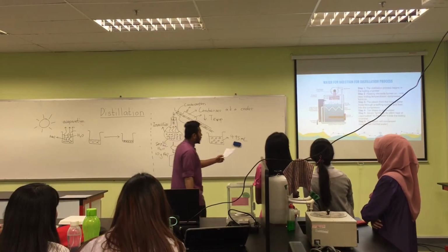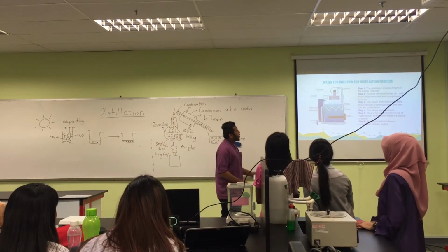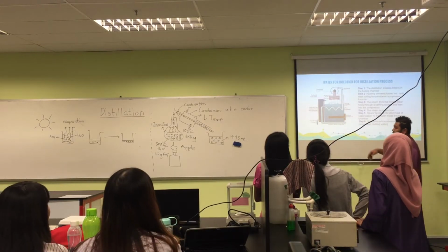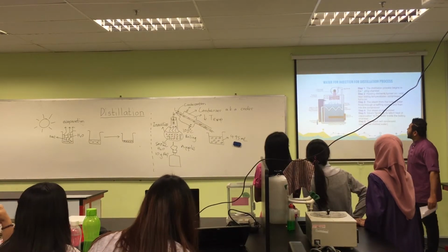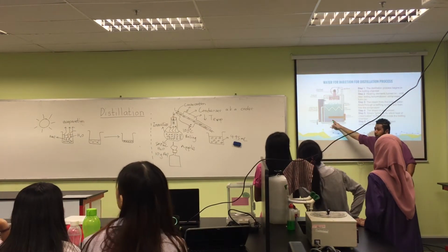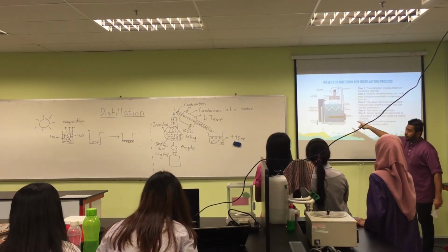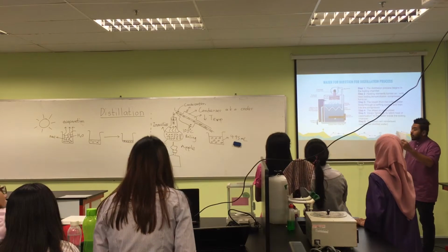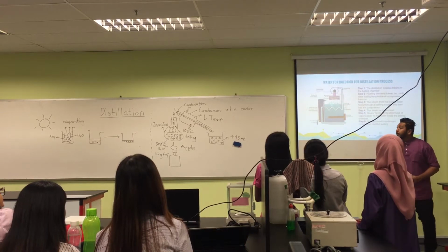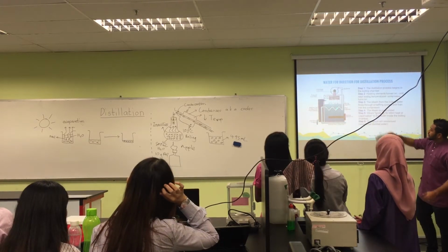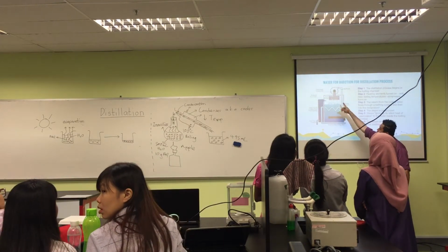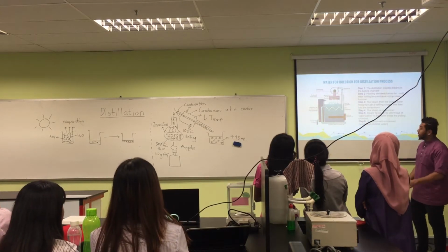The first step for producing water is the vapor compression method. The distillation process will begin in the boiling chamber. The heating element will be turned on and it will boil the water until it reaches boiling temperature, forming steam. The steam will enter the vapor system and enter the compressor, which is turned on once the water reaches boiling point. In the compressor the steam will be pressurized.